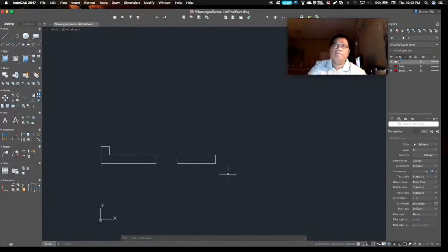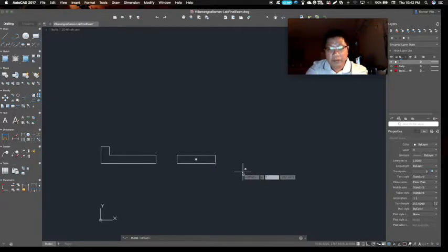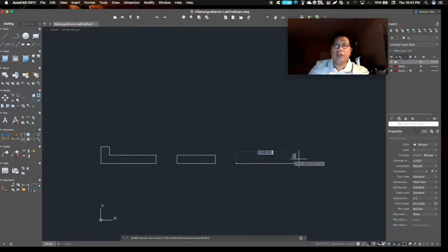Okay, here. So we get PL again, from base point here, then going to at 750, 0, then draw the line.